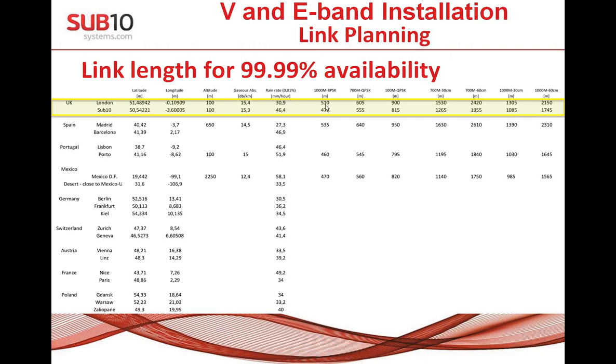It's a 40 meter difference. And if you look, for example, at E-band, it's even more, almost 300 meters, if I'm looking, for example, at QPSK modulation and a 30 centimeter antenna. This is one example. And the reason for the difference is the difference between the rain levels which you have to compensate.